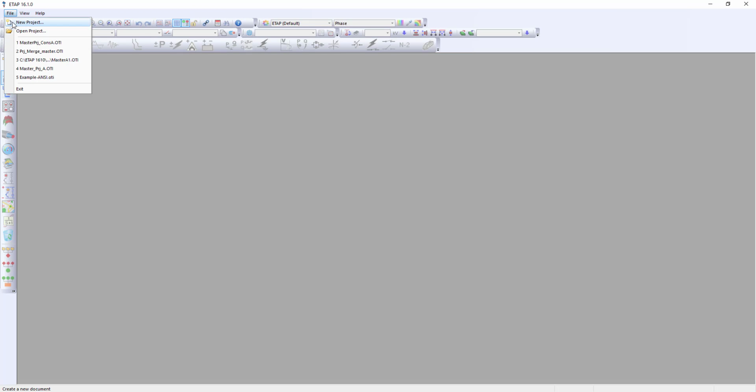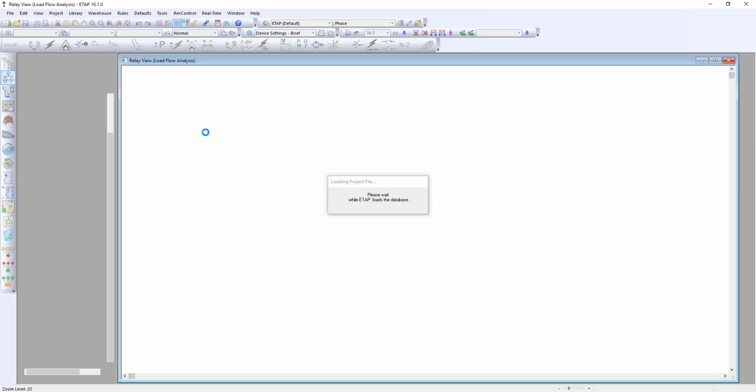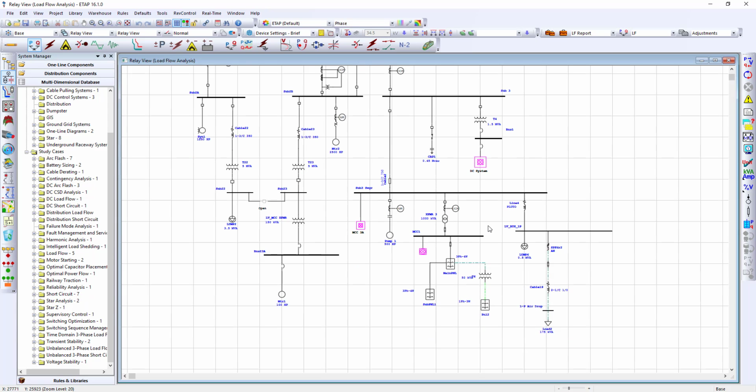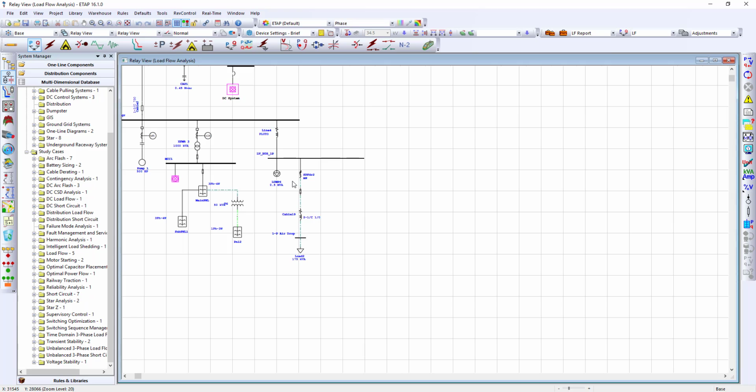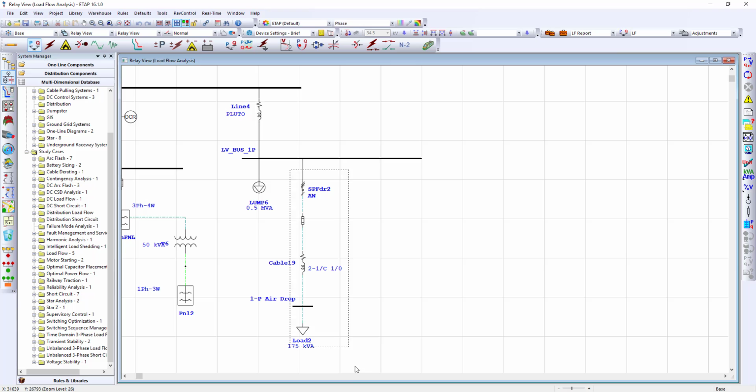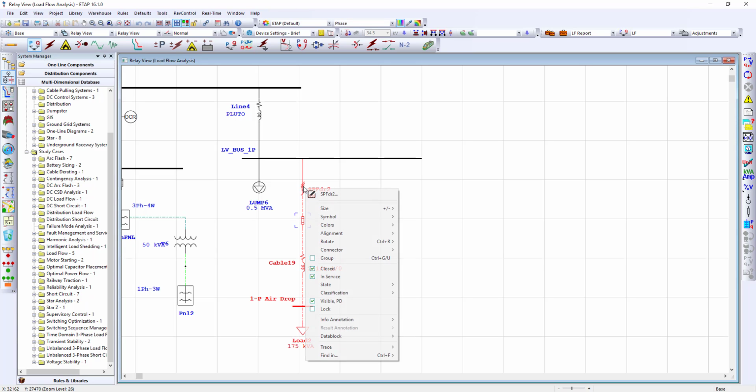Now, if you recall, we talked about doing also some kind of phase balancing at the same time that the consultant was doing the expansion. So what I've just done now is I went back to my original file. I'm the owner now. I'm logged in as the owner, and I need to balance the loads at this particular location. So the easiest way to go about it is, again, I'm just going to select the single phase branch.